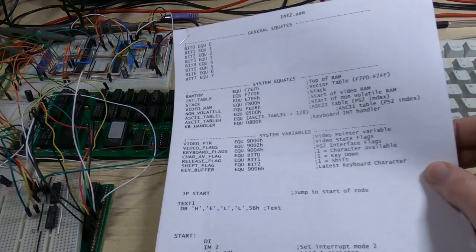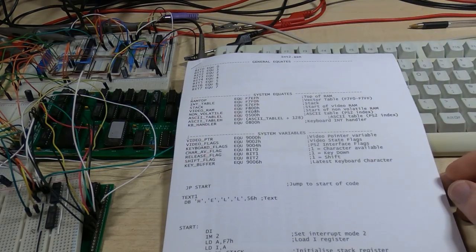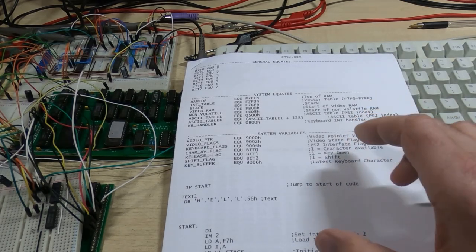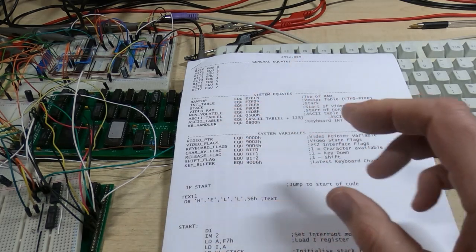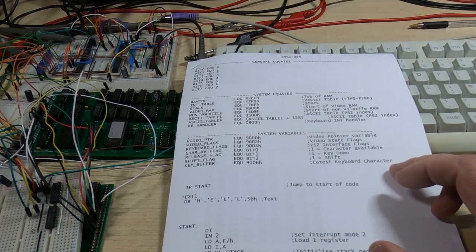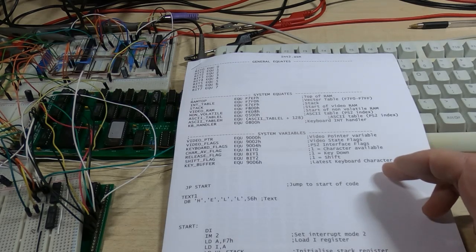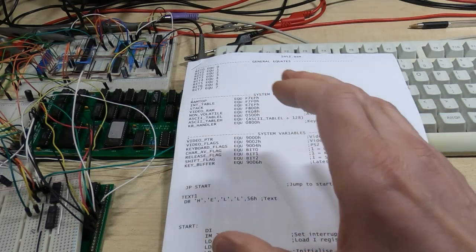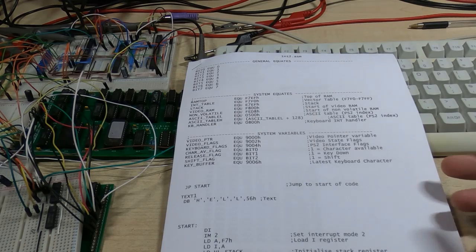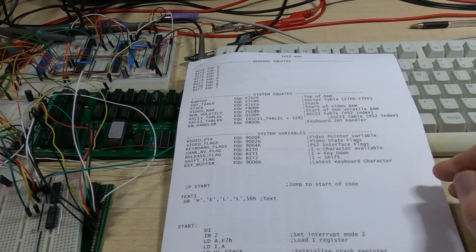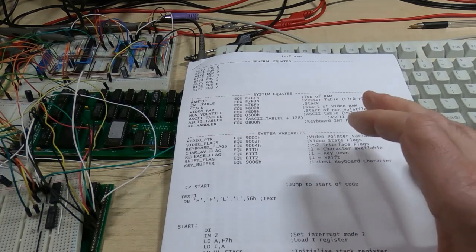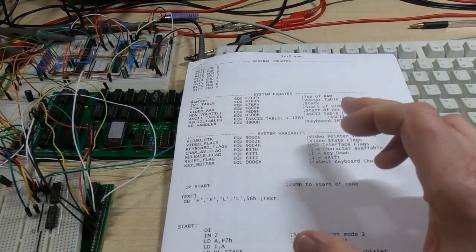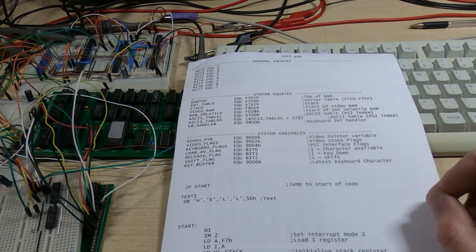So the last thing we'll do in this video is to have a look at the code for the interrupt handler. It's fairly straightforward, but one of the things that I've included is the cursor control code. The reason I've included that in the interrupt handler is because it's a very efficient place to put that. And in fact, this is what I was talking about earlier in this video when I said that not using a ready-made solution would work in our favor. And this greatly simplifies the operation of the system by not having these characters come in as ASCII code.